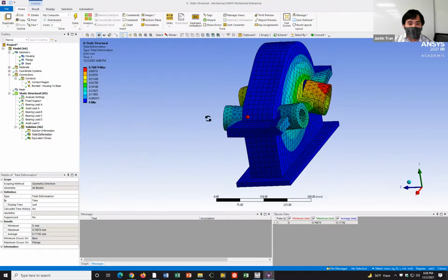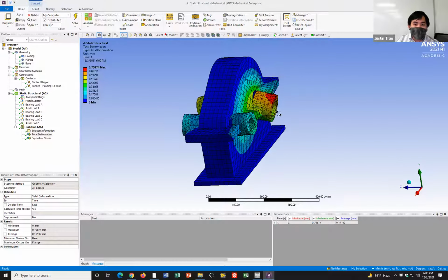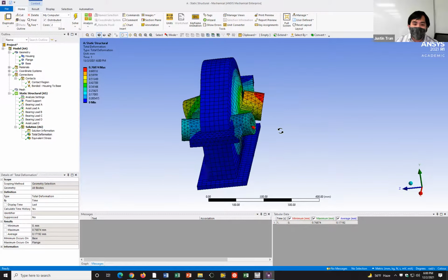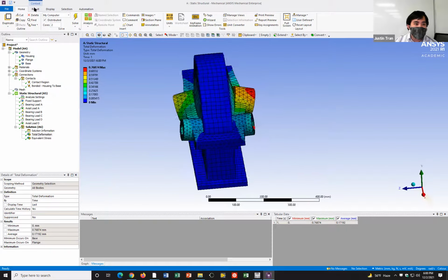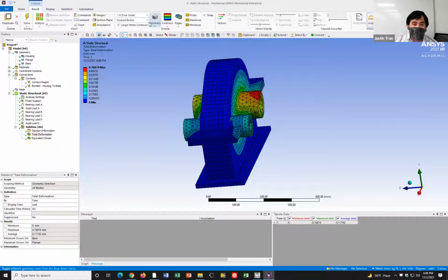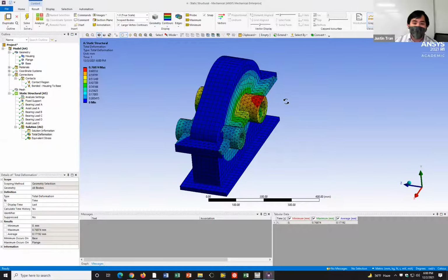And so if you set all the loads correctly, you can go ahead and run the static structural simulation, and you should get a simulation result that looks like this. It looks a little bit scuffed right now, but it's only because the results are scaled, and so it multiplied all the deformations by 53. If you want to set this to true scale, go to results and then go to true scale. And then you don't have the flanges popping off of the gearbox.